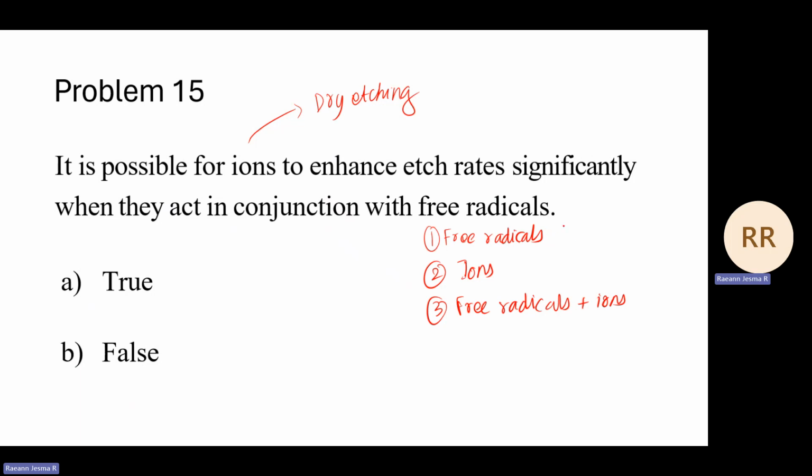If you're having free radicals, in dry etching plasma is required so that these free radicals get adsorbed on the surface of your substrate, let's say silicon, and react. Then it will form some byproduct. The byproduct will generally be volatile in nature, meaning it will evaporate as gas, and whatever reactants are formed also will be volatile.